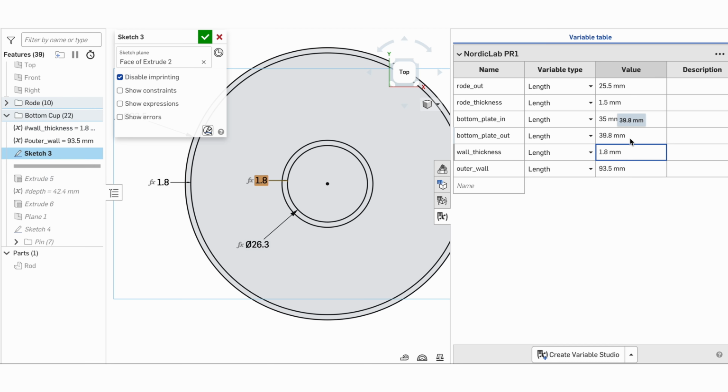As you can see here, it's a calculation: 0.6 millimeters multiplied by 3. It means I want to print with a 0.4 millimeter nozzle, set the line width to 0.6, and have 3 lines. So the outer wall will be 3D printed with 3 solid lines of exactly the same size. This is the idea, and this is how I want this kind of print to happen.